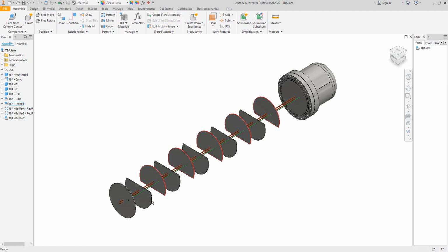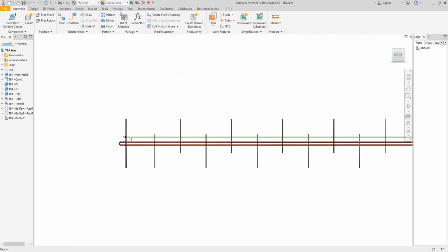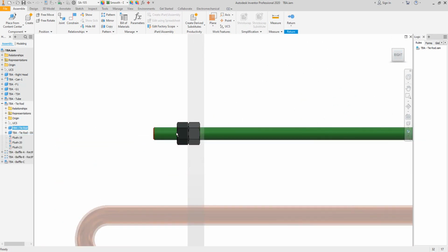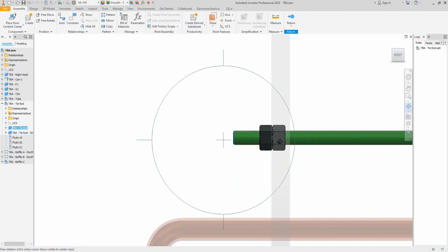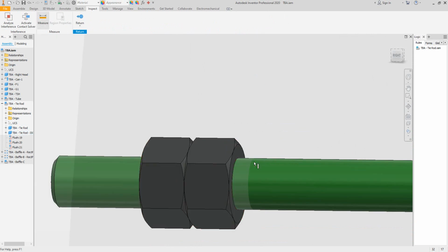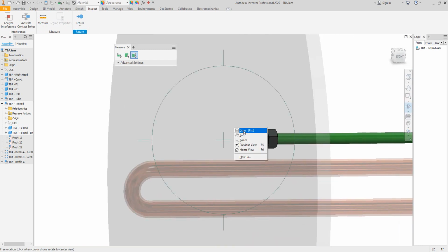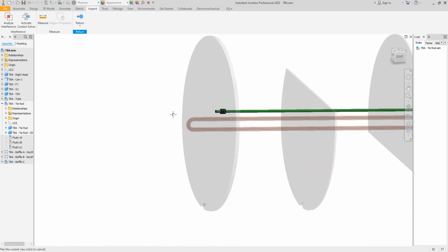Okay, here as you can see, we generate the baffles and the tie rods, and I think we may need to increase the nut spacing a little bit, so we can measure that value. So we can inspect and measure the distance between this nut from that surface to that surface and make it 33.